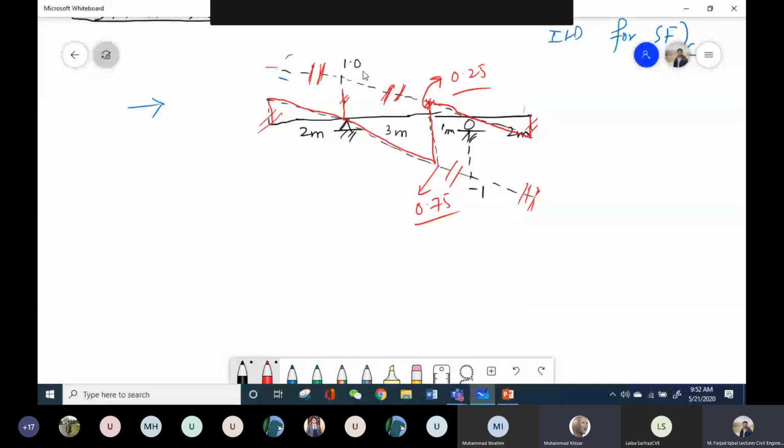No, we didn't find it from the old method. We did it from this method. For example, this is one ordinate, and for 4 meter, the triangle ordinate is 1. And what will be my ordinate for 1 meter? This one. It will be 1 is equal to 4x, so x is equal to 0.25. Okay, so this is how we did. I told you that that question is completed. This is completely a new method or a quick method.